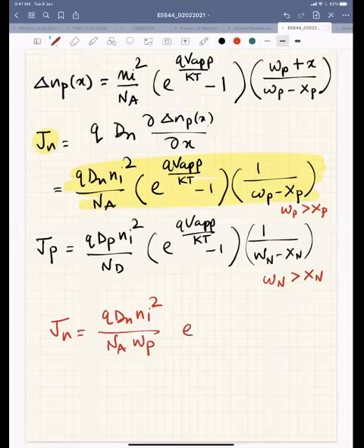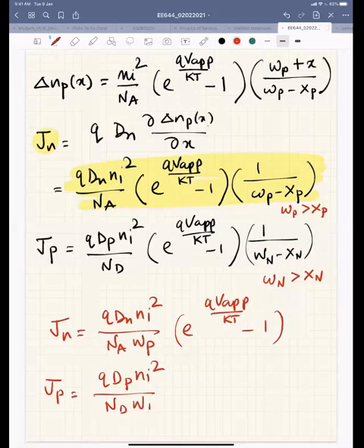Q Vf by kT minus 1, and your J_p, the whole current, is q D_p n_i squared over N_d times W_n, e to the power q Vf by kT minus 1. So these are the equations for narrow base diodes, or narrow p and n diodes. If you compare, you could clearly see...